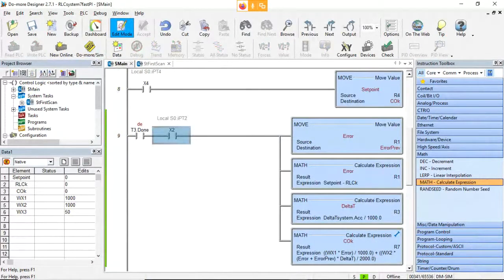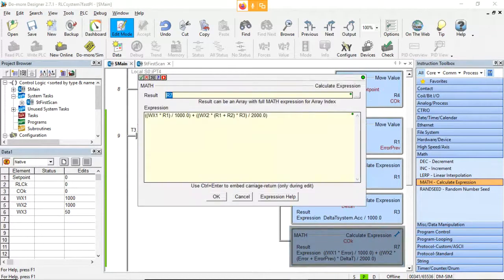Okay, but what you're doing is you're taking your error and applying it. That's your proportional control. Okay, so this amount here is your proportional control, and then you're adding your integral control. Oh, I know what I'm not calculating. This is not actually integral control here, because I'm not adding it to the previous one.